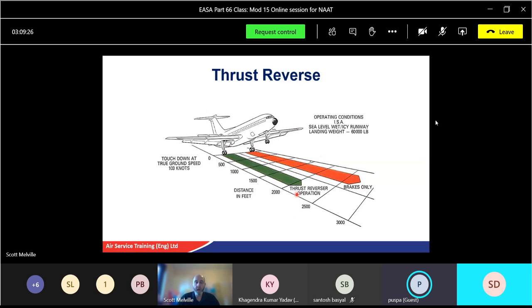Out of the two flows, primary and main flow, which one is always available when you open the high pressure cock? Primary fuel flow. Yeah, it's always available. It's not as much as the main one because we don't want all the fuel to start with when we start an engine. As soon as he opens the HP cock, that fuel flow is available. There are no distributor weights. Otherwise, if we put too much fuel in straight away, we can get hot spots and over-fuel the engine, which we don't want either.